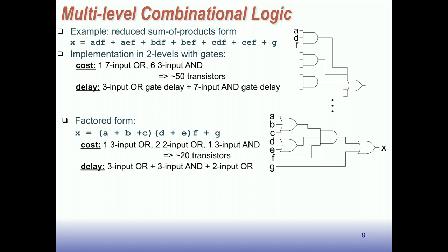Oh, and by the way, somebody asked the other day about the complexity of Boolean simplification, and I looked it up, and these problems are all NP complete. The 2-level simplification is, and multi-level logic simplification is NP complete at least. Very hard. And so the programs that do this use heuristic algorithms. So that means you probably get different results depending on which program you run.